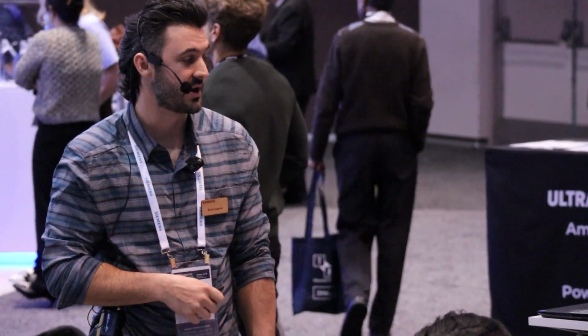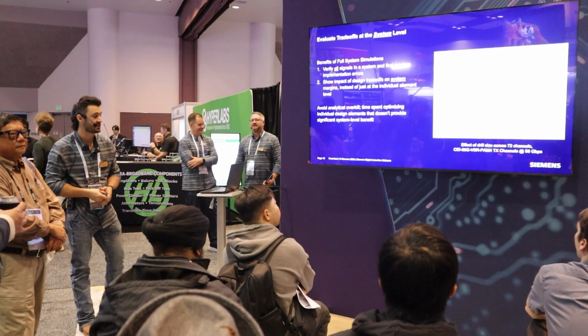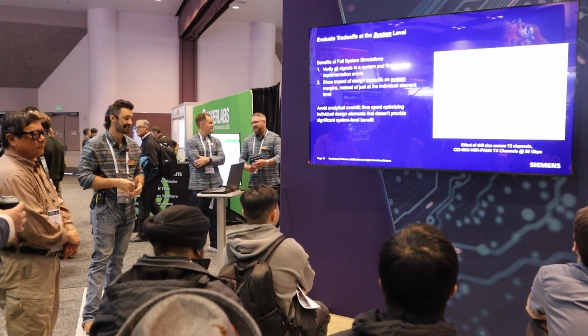There are two major benefits to running these full system simulations that I've been talking about. The first is that we can perform the post-layout analysis to verify all of our signals on the board rather than just a select few of them, and we're able to find some of these random implementation errors in the system. And the second benefit is that we can show the impact of design trade-offs at the system level and how they affect all of the signals on the board.